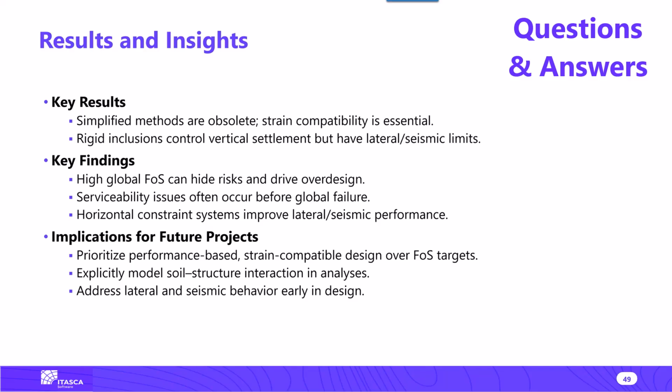Well, it's not for me to speculate on what you did in your model. Typically, if you're using Mohr-Coulomb for concrete, you have to go through a calibration process. You have to use strain softening in order to be able to capture the compression side, go up to the peaks, and you usually do that by implementing a table. So essentially changing the cohesion as a function of the plastic strain, and you do the same thing for the tension.